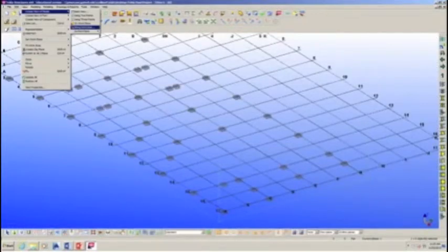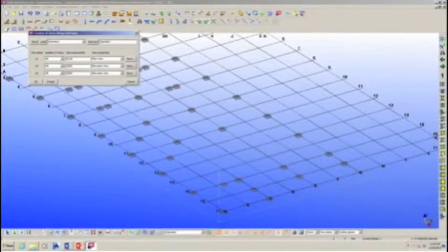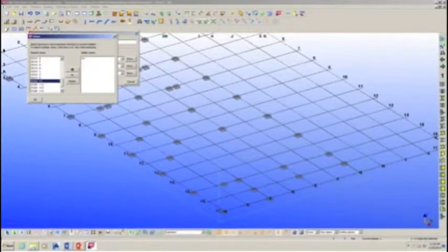Sometimes it is easier to create your model from different views. To select these views, select Create View of Model and Along Grid Lines. This is the box that will appear. Select Create. This Views box will appear. Scroll down and select the view you would like. In this case, we'll be using Plan plus 0.